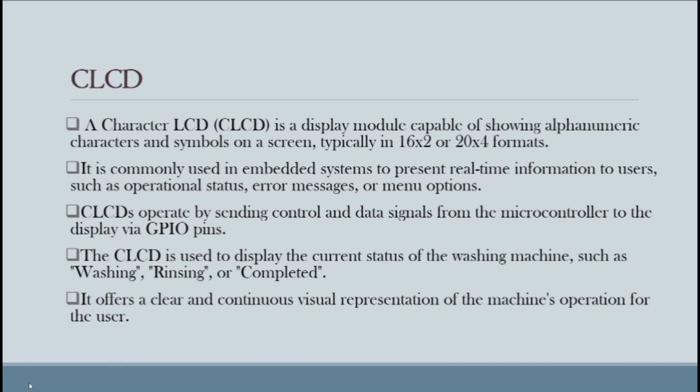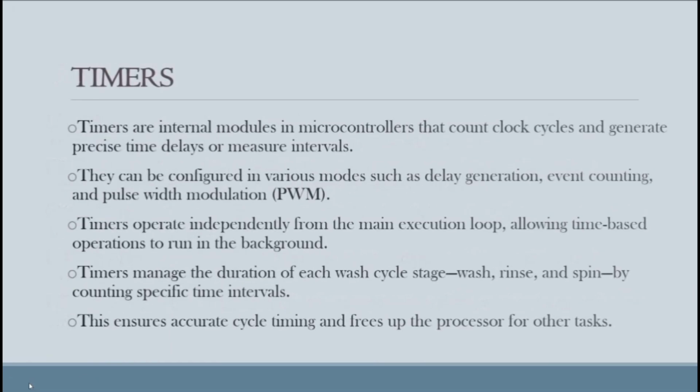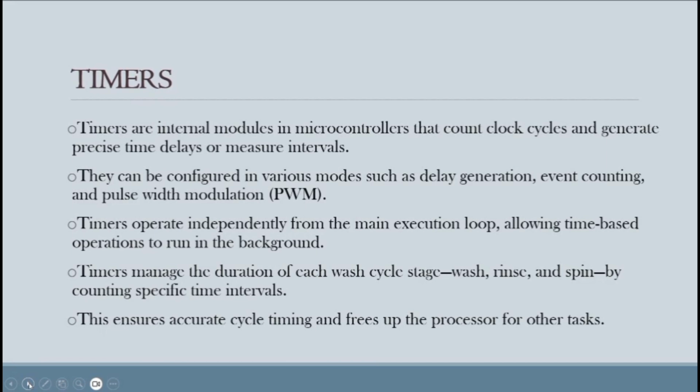Next one, timers. Timers are internal modules in a microcontroller that count clock cycles and generate precise time delays or measure intervals. They can be configured in various modes such as delay generation, event counting, and pulse width modulation, PWM. Timers operate independently from the main execution loop, allowing time-based operations to run in the background. Timers manage the duration of each wash cycle stage, wash, rinse, spin, by counting specific time intervals to ensure accurate cycle timings and free up the processor for other tasks.